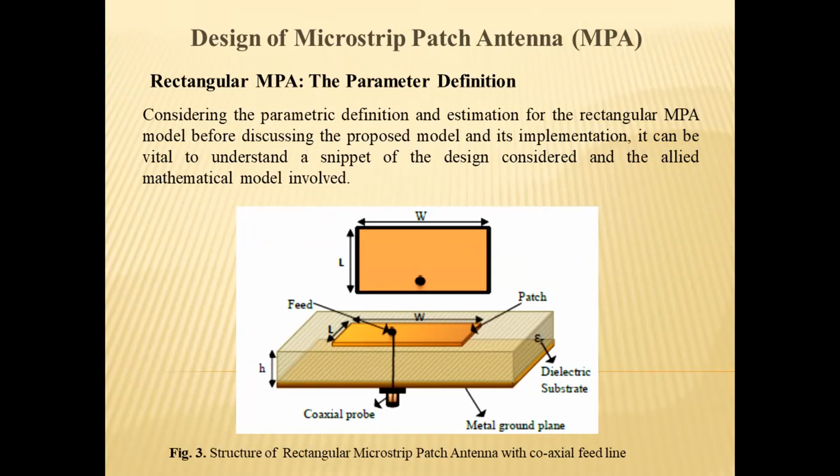To obtain the final design solution, adaptive genetic algorithm ANN requires different training parameters with the resonant frequency in the ultra-wideband ranges. At first, the resonant frequency of 4.99 gigahertz is considered with the dielectric constant of 4.4, while the height of the dielectric substrate was maintained at 1.6 mm respectively.